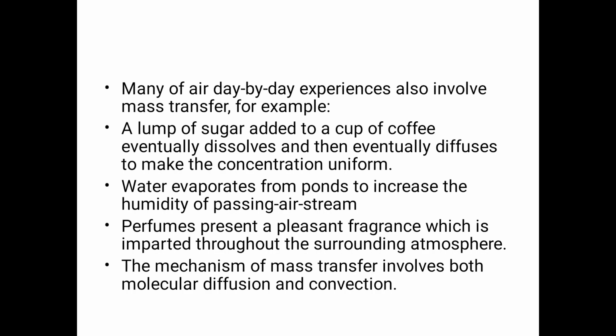In real examples, many of our day-to-day experiences also involve mass transfer. For example, a lump of sugar added to a cup of coffee eventually dissolves and then diffuses to make the concentration uniform. Water evaporates from a pond to increase the humidity of passing air. Perfumes present a pleasant fragrance which is spread throughout the surrounding atmosphere. The mechanism of mass transfer involves both molecular diffusion and convection.